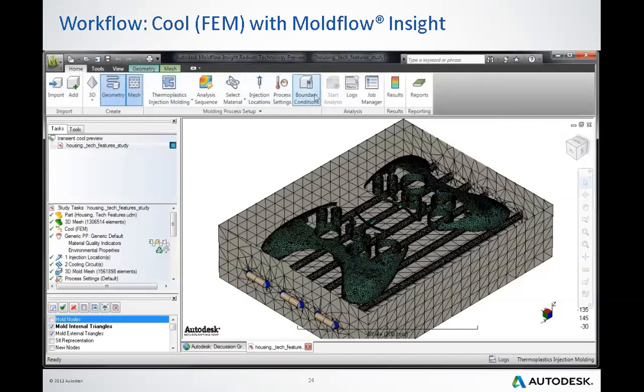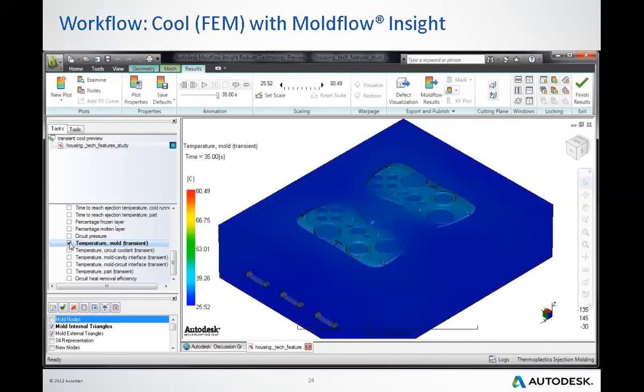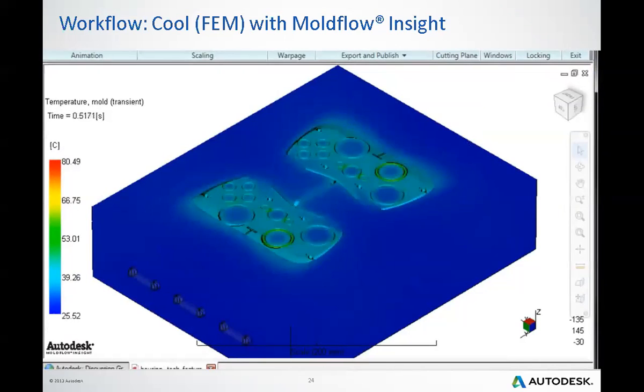And then we can analyze the result and see what happened in our model. Once we have Moldflow, we can reduce the cost of making physical prototypes to test many things. And after we get the result from Moldflow, we go into the machine and adjust something, and that's close to our requirement. You can see from this picture showing clearly the temperature in the mold.